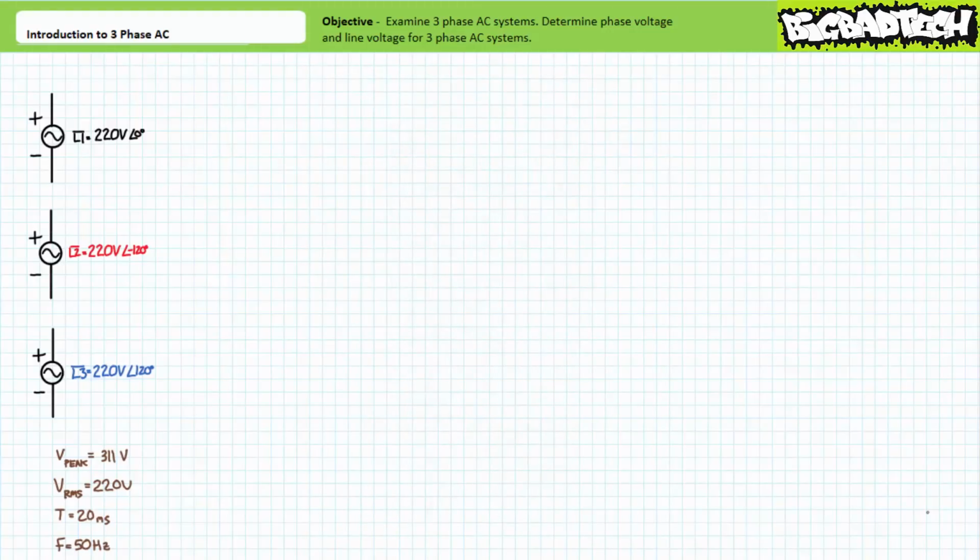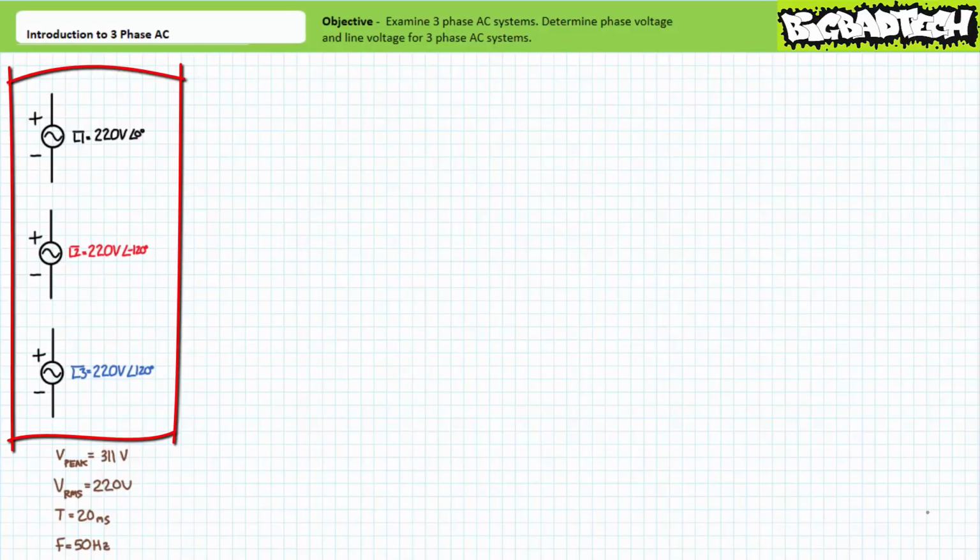Let's start with the basics, and then I'll come back to fill in the details. First, we can visualize the three windings as three independent sinusoidal AC voltage sources, each with the same magnitude and frequency, however phase shifted from each other by a relative 120 degrees.